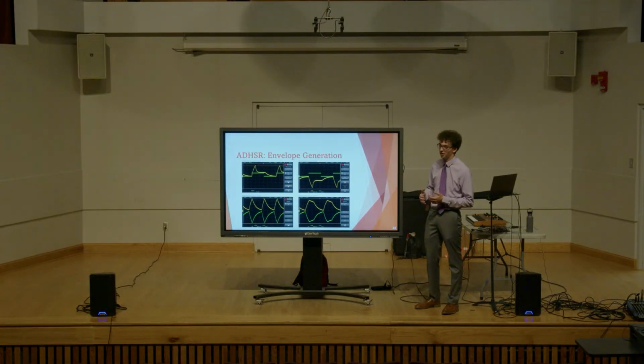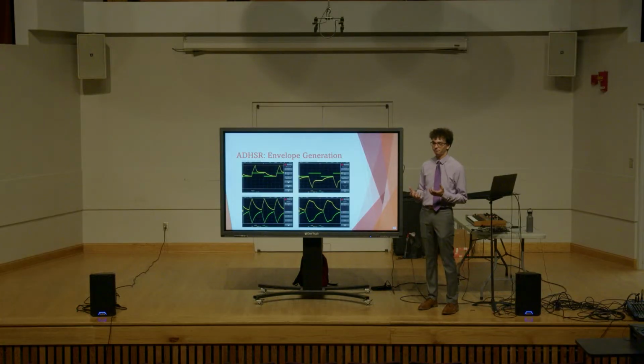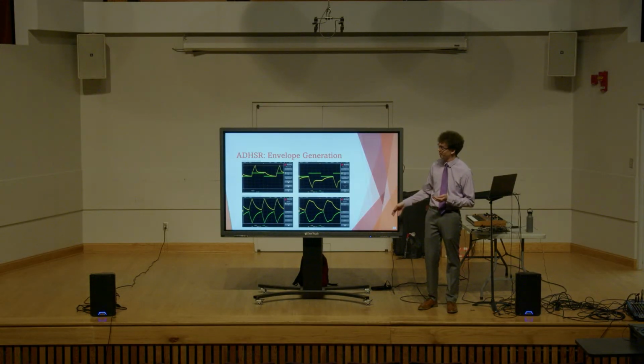So if the gate turns off during any one of those phases, it immediately stops and moves to the release phase, which is the end of the ADSR cycle. And then, I don't know if you can see it very well, there is a brief hold implemented so that when the gate releases, it does not immediately proceed to its release phase. And so that isn't a feature that I will be using a lot, but it is a feature that is very interesting in the looping mode, which is shown on the bottom here.